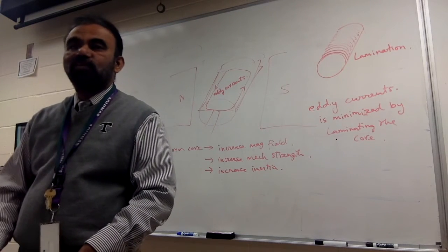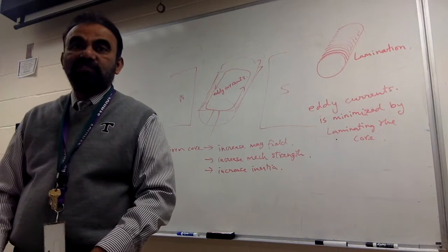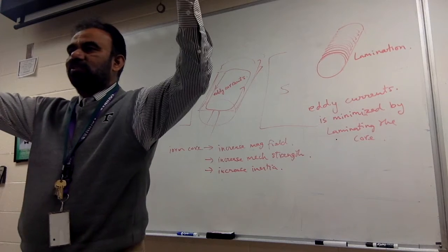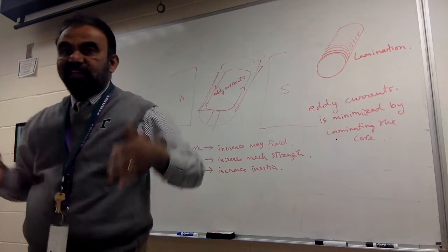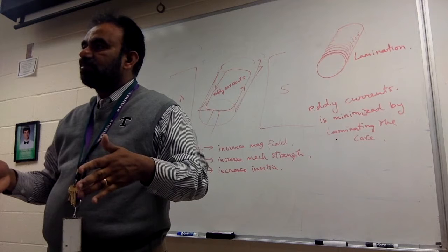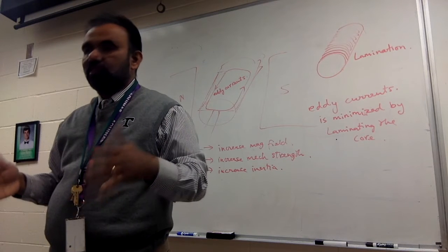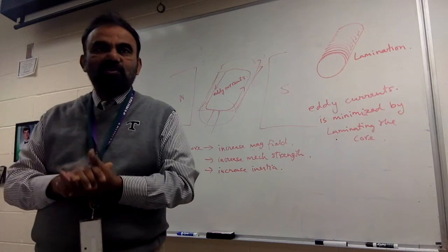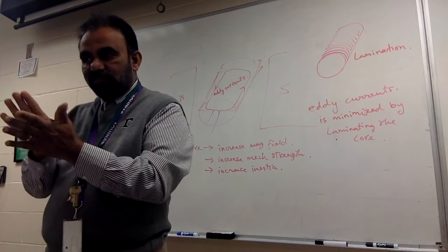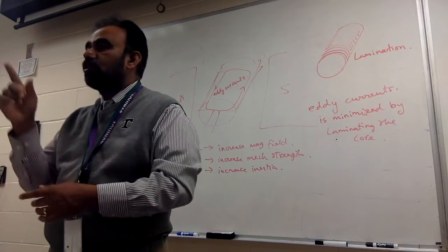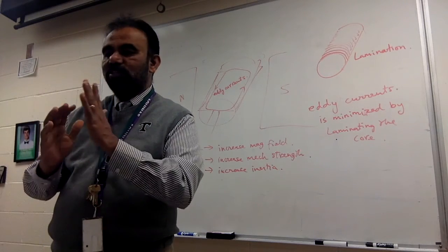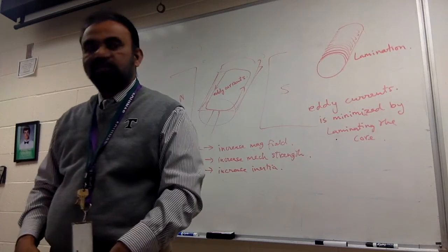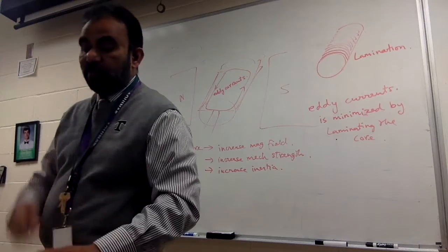They use magnetic brakes when the physical brakes are not going to be very effective. Like big structures, like those big cranes, they're on rails. And those big structures, if they already start moving, it's hard to stop them because normal braking devices don't work that easily. The friction effects are not good. They use magnetic brakes. So when the wheels spin and you turn on the magnetic field, it applies brakes. So eddy currents are useful in magnetic brakes.